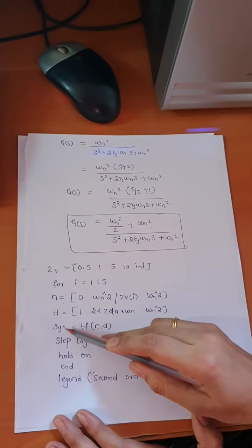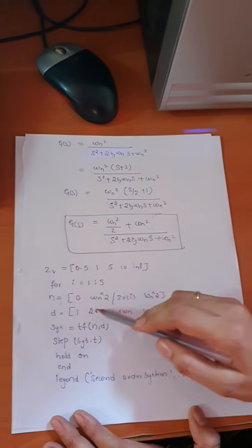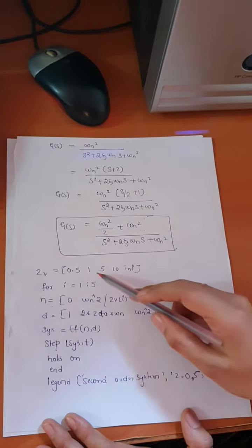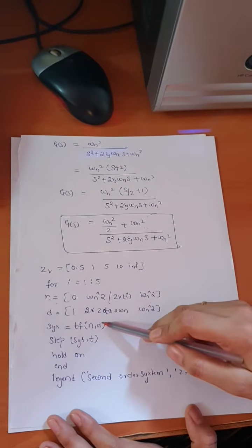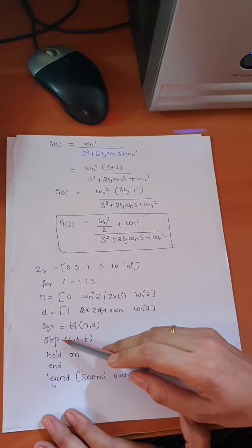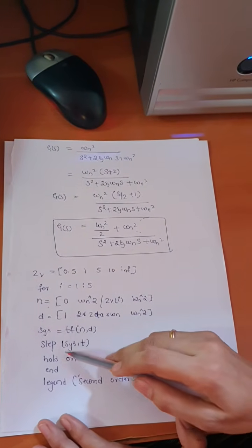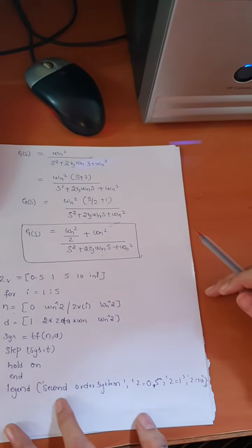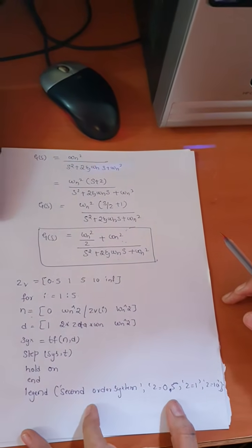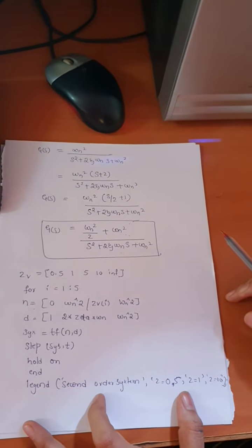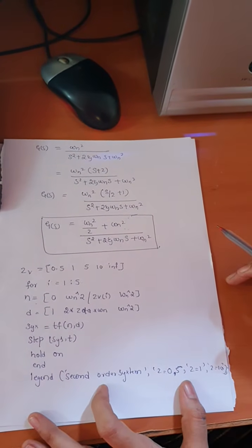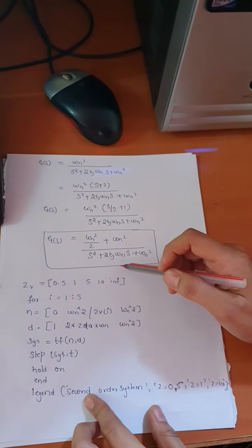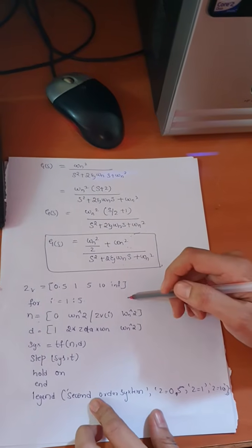Then define a system, because this is our new transfer function. Here also the omega n, zeta and zero values need to be substituted. So totally 5 transfer functions we are going to obtain for this program. Then we need to plot a graph by considering the step input. Again we need to put a hold on command and legend. Why is this legend command required? Since we are getting 5 zeros in our graph, to identify which zero values correspond to which curves, we need to put a legend command, so that each graph is represented with a different color. So this is the second program.